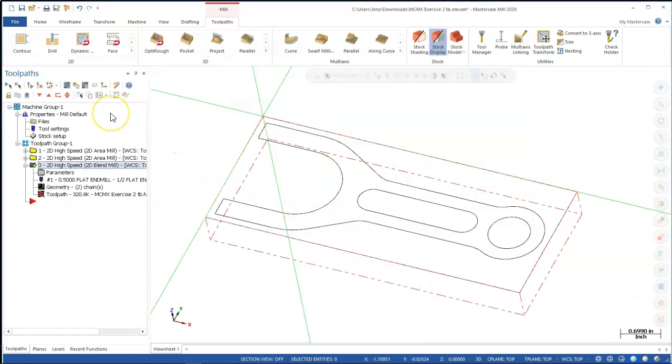Did you use dynamic for finishing or just for left? No, the finish pass is still going to go back to a standard, yeah, but you're not going to have the same level of control that you will creating a separate contour. If you can get away with it and it's not critical, you have a nice, plus or minus 5 tolerance that we're probably going to be able to hit.